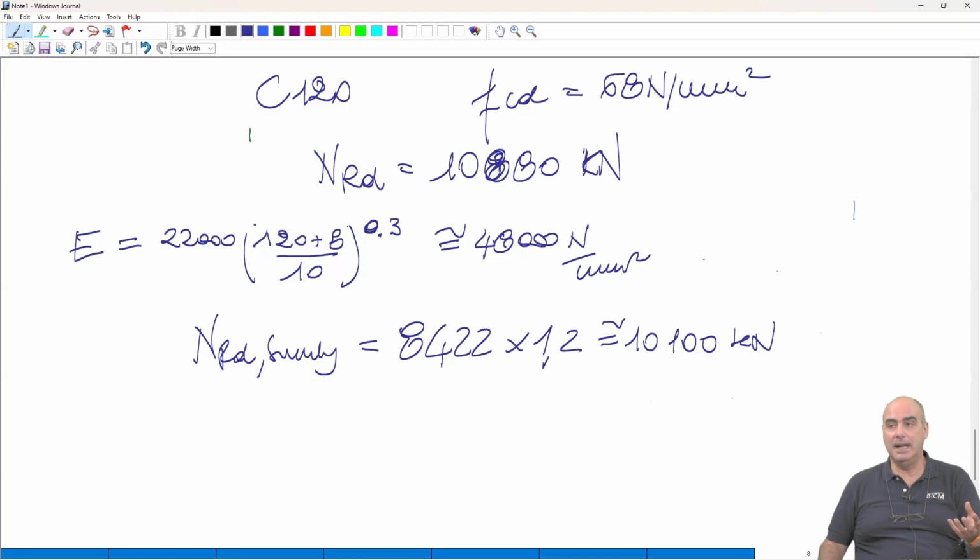And since the ratio of reinforcement that we put in the column is proportional to the area of the concrete, it's good that if we reduce the size of the concrete, we will also proportionally reduce the steel. But the reduction that we can allow is not absolutely proportional to the increase in the strength.